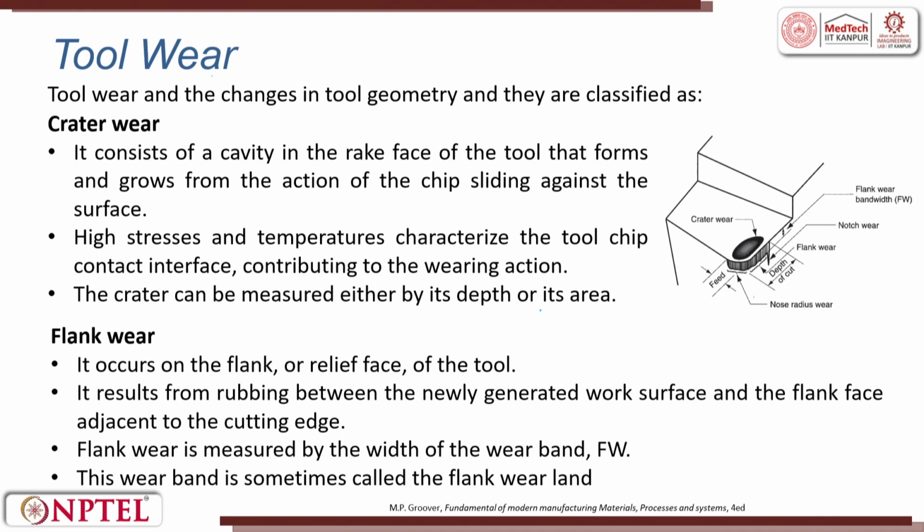The crater is very difficult to measure because it is erratic in nature and the depth is also erratic. So, we have to measure the depth to do it. Generally, what we measure is the flank wear, which happens along the relief face. As and when the cutting happens, there is a gradual wear. Here, I have linked the feed which is given and the depth of cut with respect to machining, and now you try to figure out the amount of wear which has happened.